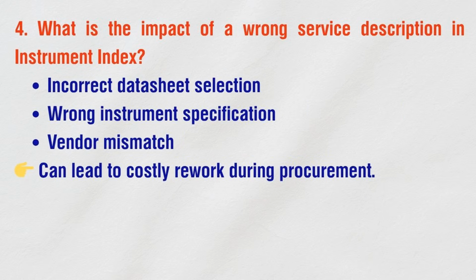What is the impact of a wrong service description in instrument index? Incorrect datasheet selection. Wrong instrument specification. Vendor mismatch can lead to costly rework during procurement.